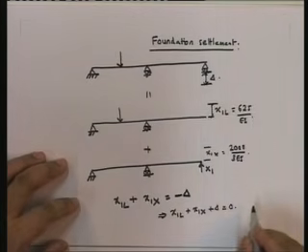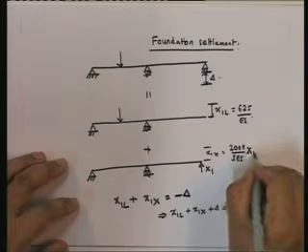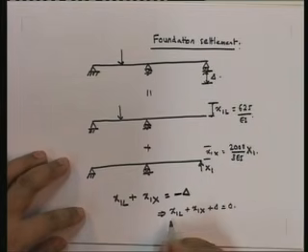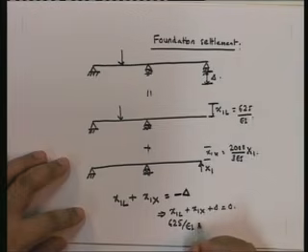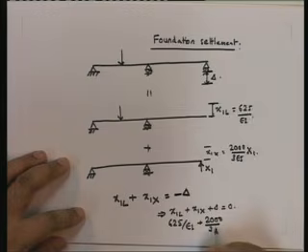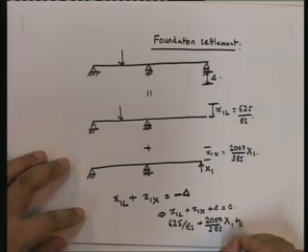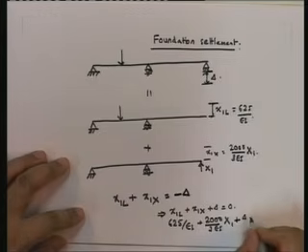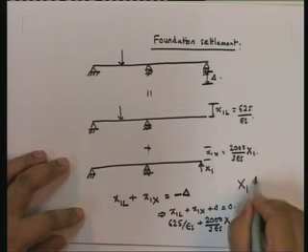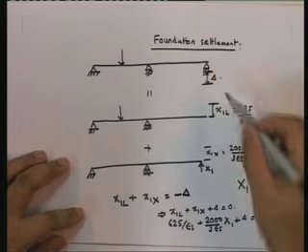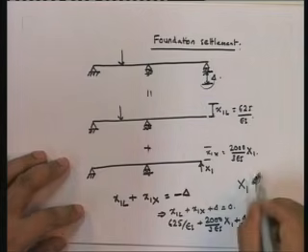And if you really look at it, this is going to be 625 upon EI plus 2000 upon 3 EI into x1 plus delta is equal to 0. And the value of x1 goes up because of the support settlement.